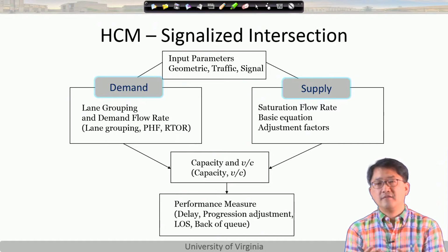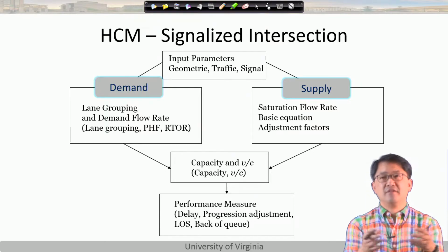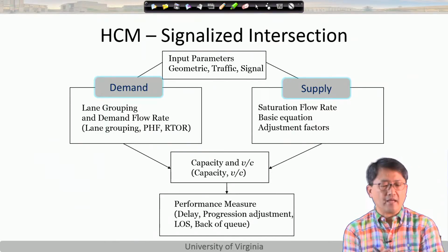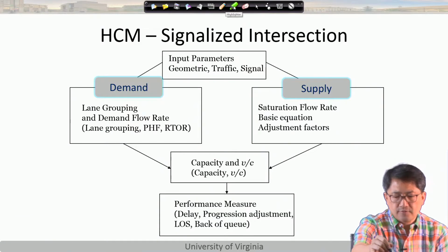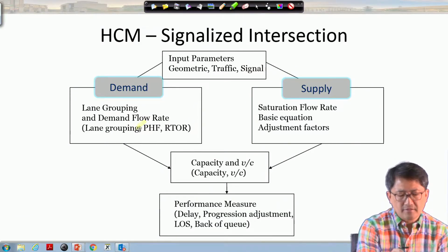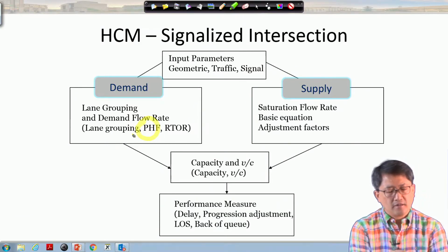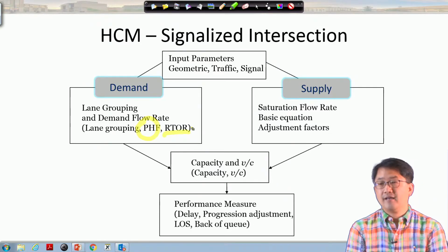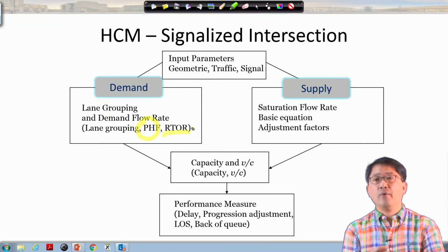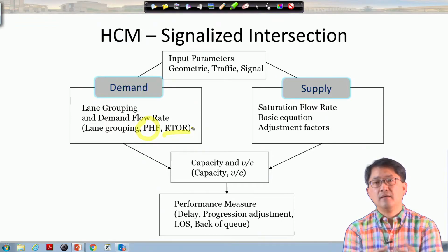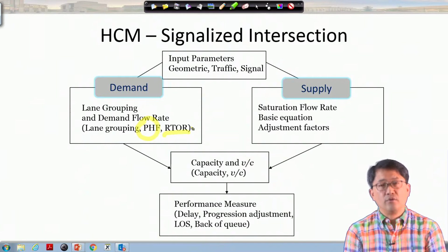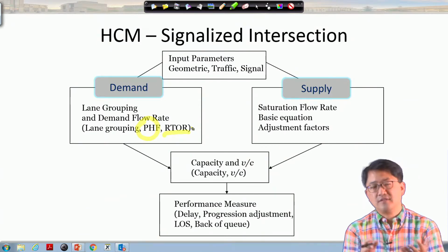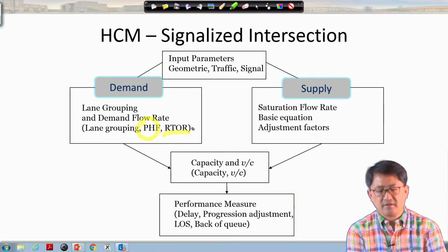And the worst case is that worst 15 minutes happening at the same time. We probably want to deal with it instead of average conditions all the time. So that's looking at conditions for this peak hour factor we mentioned. And then this should be a left turn on red, I guess. So cars go away even though they don't get the green, they can just make left turns. And also defining lane groups is another concept which is fairly straightforward.